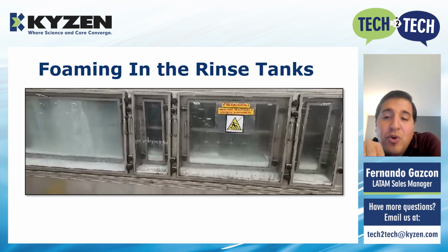The boards could drip down the excess of liquid back to the wash tank before reaching the rinsing stage with this change. Nevertheless, the foaming continued to appear in excess. Therefore, we focused on the second most usual cause for this, which is the DI water quality.